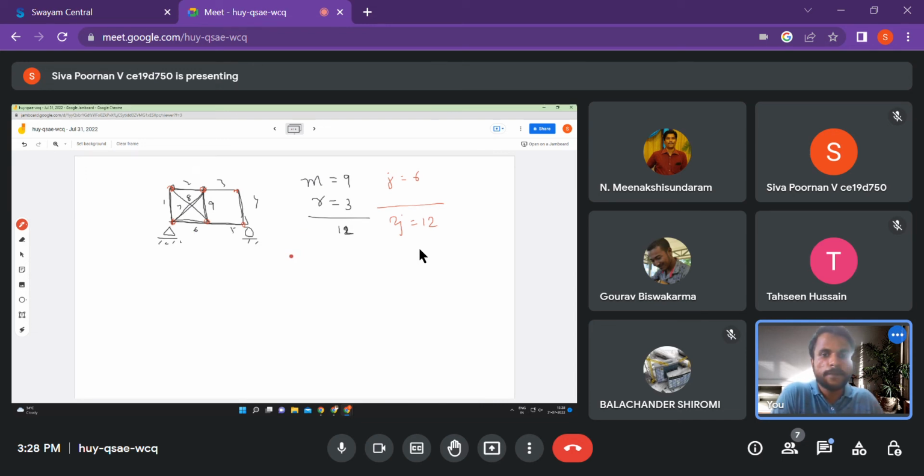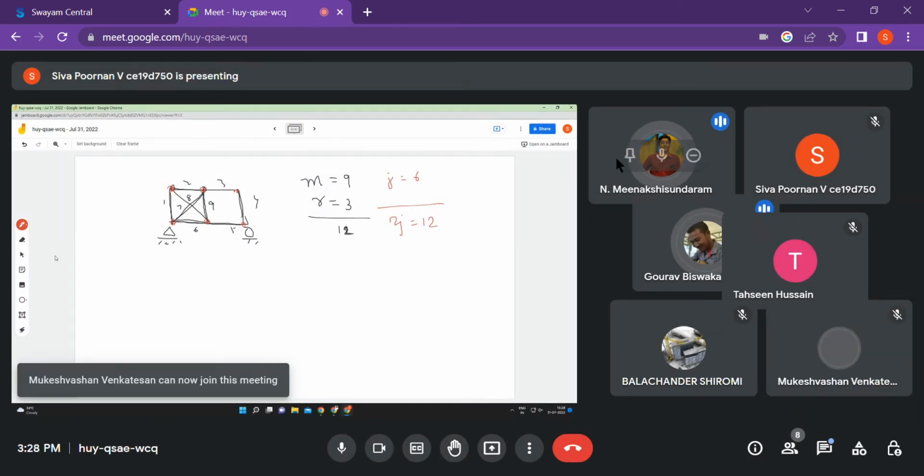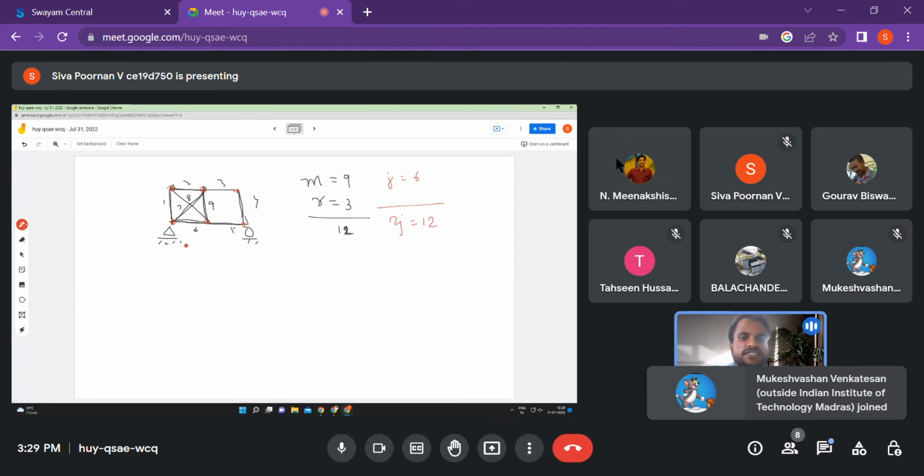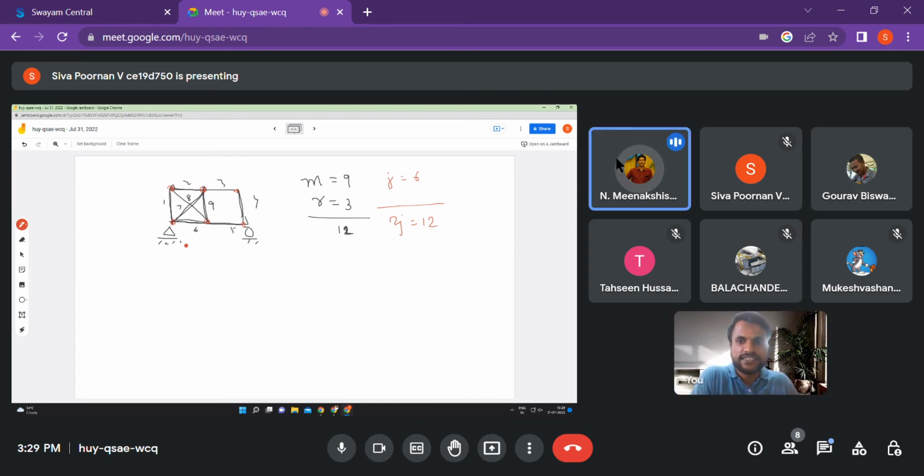But is it statically determinate? Unstable. Why is that? Which is deficient, which is redundant. There are both of these things in this. Yes, you are right. So actually, if in the same structure I take one of these bars and put it in the diagonals of the other rhombus, so let's say I'm taking this portion and putting it here, then this would become statically determinate, right? So then what is the problem with Maxwell's rule? Why is it giving a wrong indication?